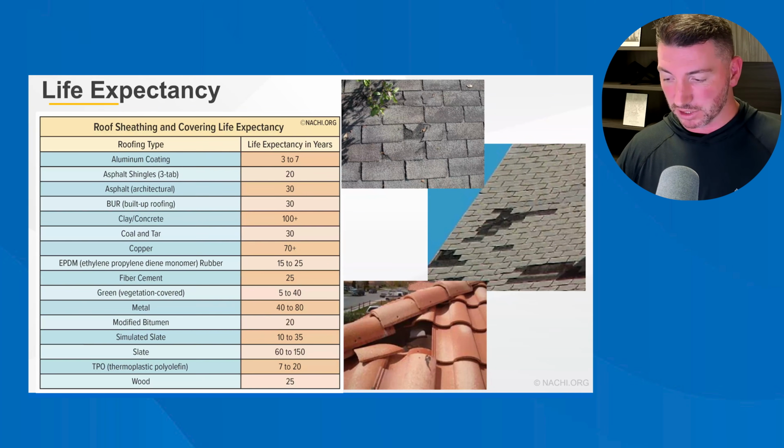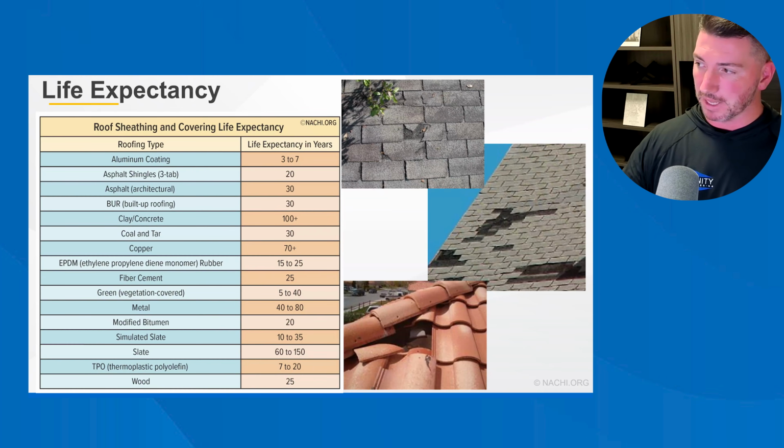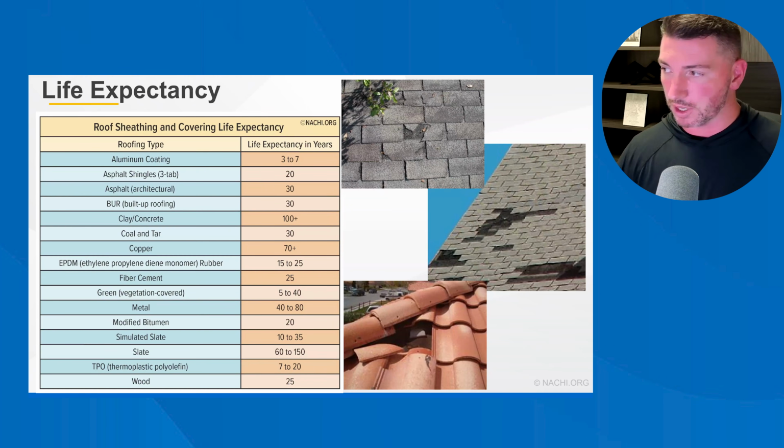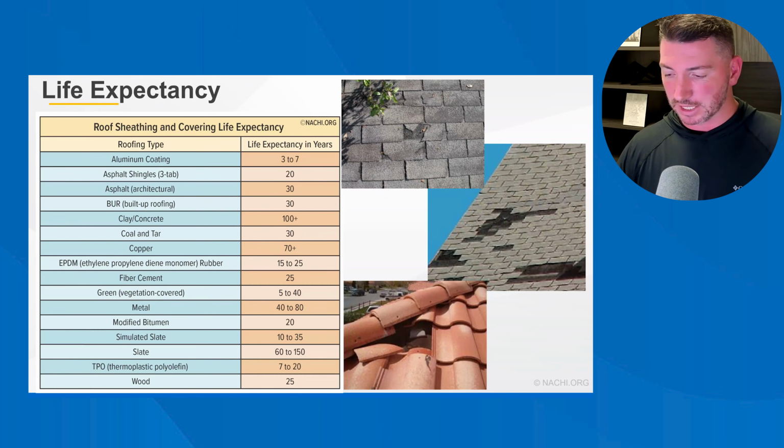The inspection image above is of missing shingles blown off by high winds. And the inspection image they're talking about is the one in the middle to the right. The one all the way up is tree rub, but the one in the middle is shingles that were blown off by high winds. Roofs in areas that experience severe weather, such as hail, tornadoes, and hurricanes, may also experience a shorter than normal lifespan overall, or may incur isolated damage that requires a repair in order to ensure the service life of the surrounding roofing materials.